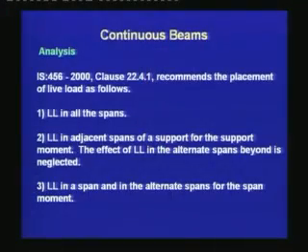IS 456-2000 clause 22.4.1 recommends the placement of live load as follows. There are 3 load cases for the live load that has to be considered. First is, we should place the live load in all the spans.